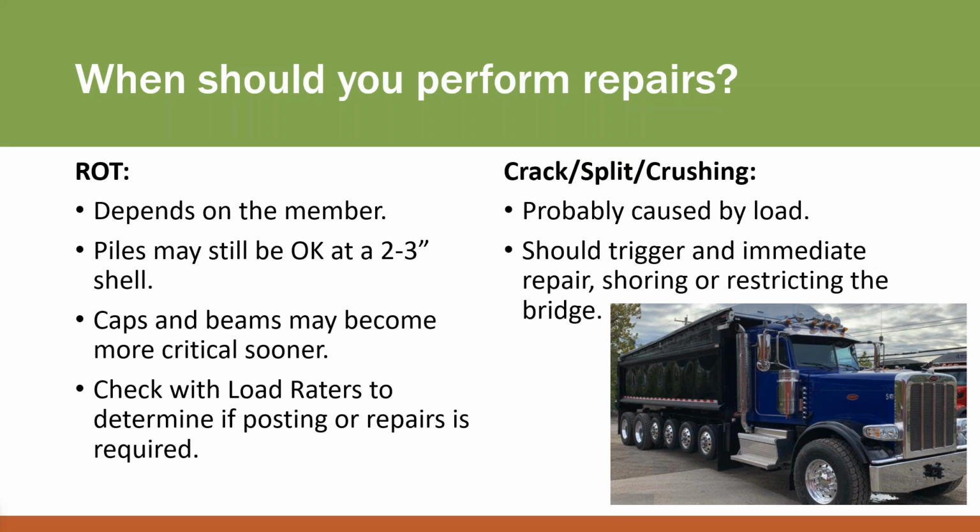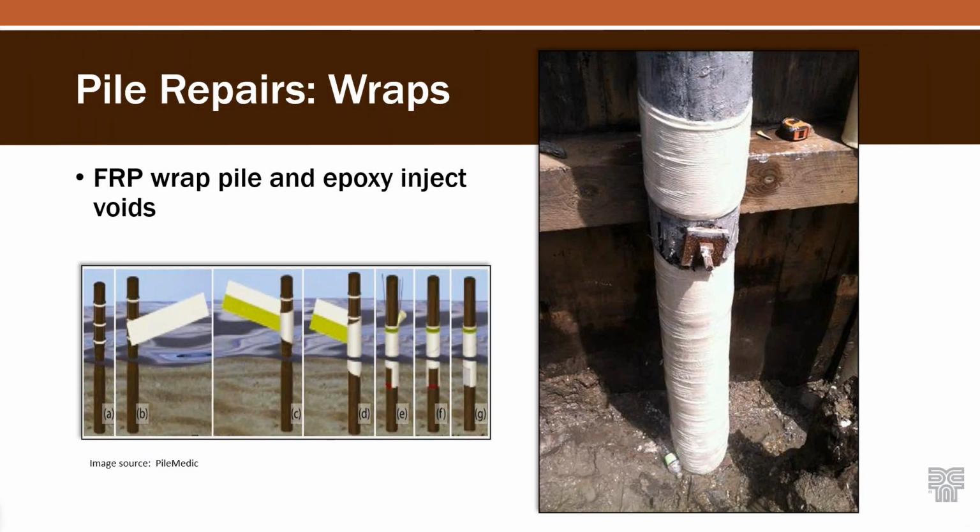But when you get these trucks on timber structures, which are typically shorter span, then something that used to be spread out over a lot of axles and a long distance at 80,000 pounds can actually get the whole weight right in your span now. And I think they're disproportionately picking on our timber structures. I don't have anything more than anecdotal information on this, but I feel like I've seen more cracks in timber girders since these trucks have become more prevalent. And you probably have seen a lot of posting signs for them as well, and probably noticed a lot of those are targeting your timber bridges.